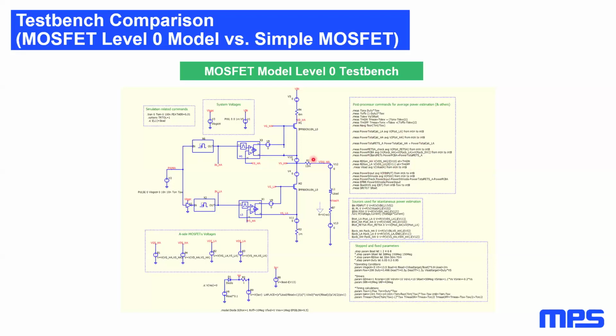One consideration must be made about the drivers. We have developed a driver model that almost ideally controls the slew rate of the switching node. In a few words, these drivers pump and drain the exact gate current needed for the MOSFETs to ramp up and down the switching node at a constant slope.